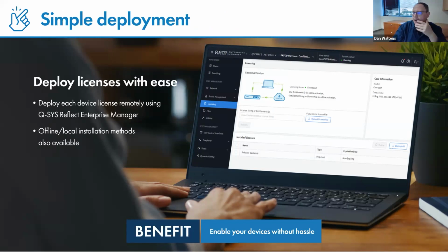Any recommendations? If you go to our FAQ page on the Q-SYS website, under support, there's a question there, and if you just type in NV32 power supply, it talks about the ones that we've recommended as PoE injectors. There's two different ones, a Phihong and a Microsemi. But then there's an update that says internal testing and reports from the field found inconsistent operation using the following PoE injectors powering the NV32. These injectors are not recommended. So we list a couple of them in there.